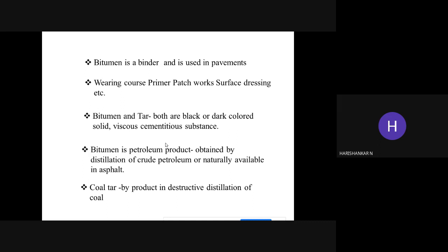On the subgrade soil you can see the sub-base course, above that the base course, and above that the surface course. The surface course mainly consists of a rich quantity of bitumen, because of two reasons: the water tightness and the wear and tear. Below that, it's mostly composed of aggregates.